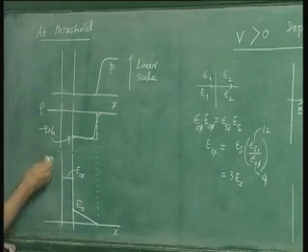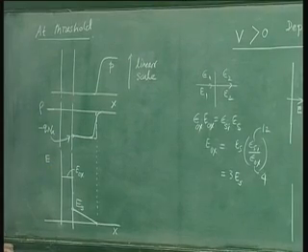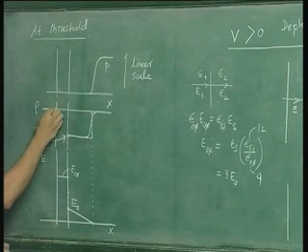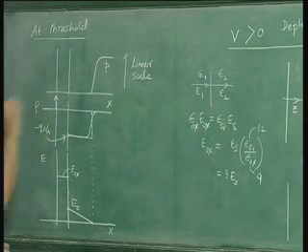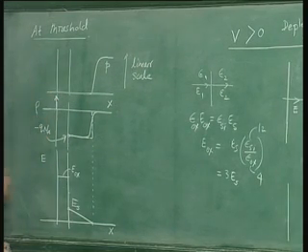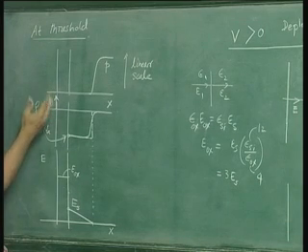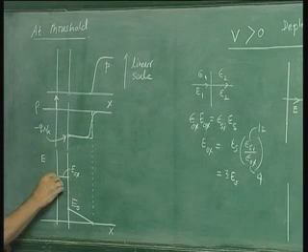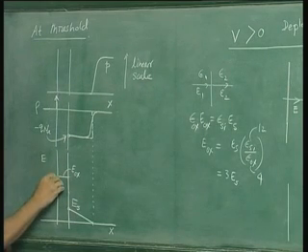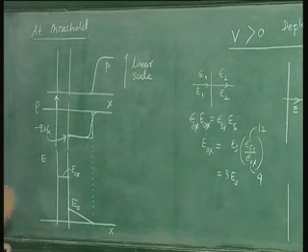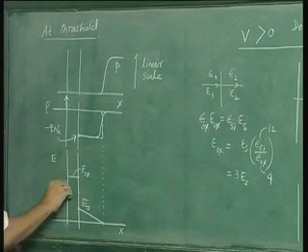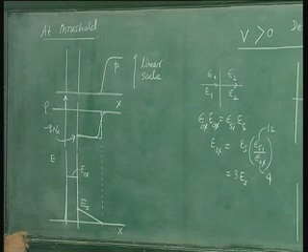Now what happens in the metal or gate? Obviously you have the opposite charge. So here you have the charge shown by a delta function on the positive side, because you have a positive charge. So the electric field will abruptly drop to 0 in a small distance. That field is not of interest because it falls abruptly in the metal.